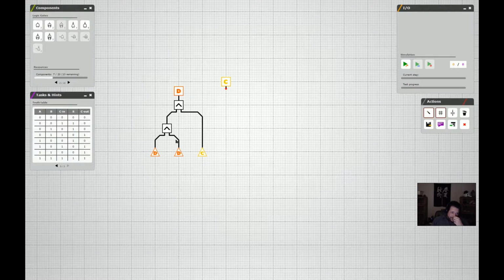So now, if we look at where can we pull a signal off of here to get our carry? What are the conditions where carry is a 1? Well, carry is a 1 when B and Cn, carry in, are 1s. It is a 1 when Cn and A are 1s. It is a 1 when A and B are 1s, and then it is a 1 when everything is a 1. So let's think about that. When everything is a 1, right?